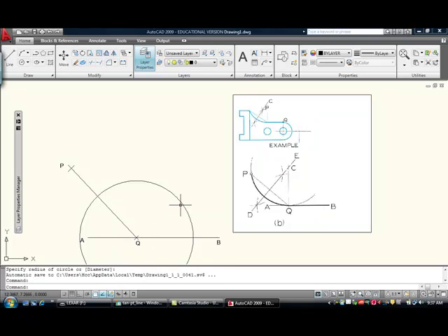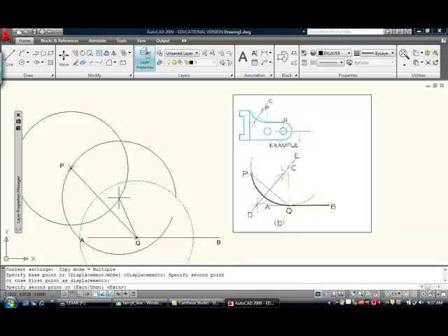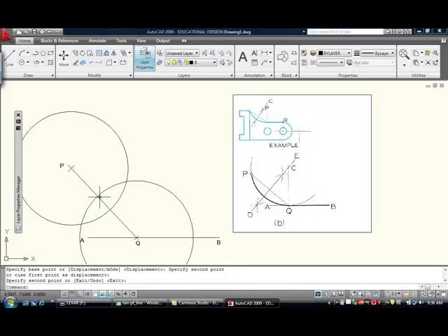Okay, and since I have to have the same radius at this next point, I can just copy that circle. So using my object snaps and selection modes, I can go ahead and just copy that circle. Okay, that gives me the two points that I need to work with in order to construct my bisector to PQ, which could be a line from an intersection to an intersection.